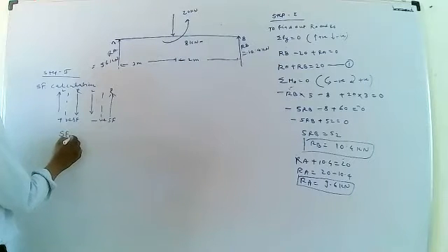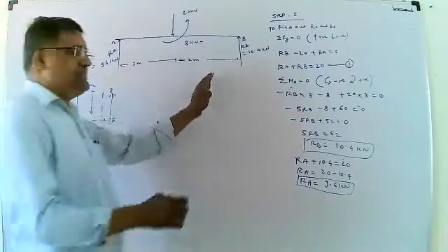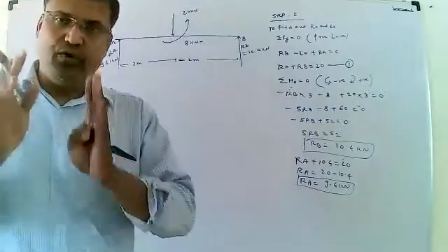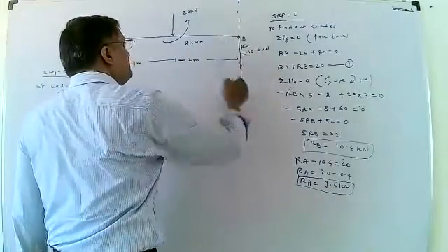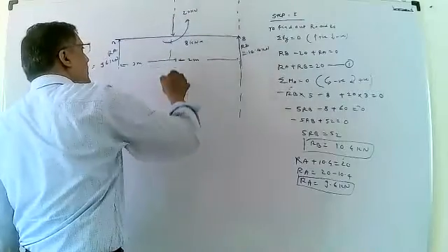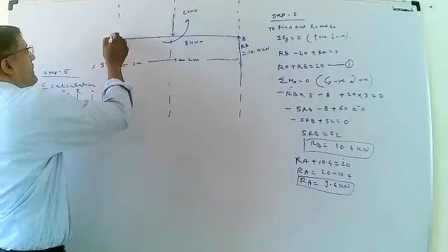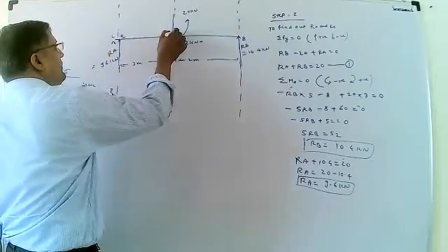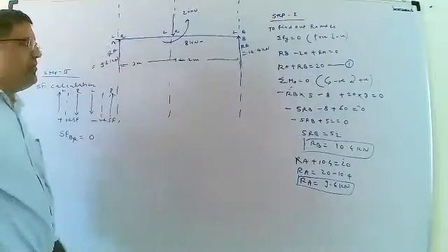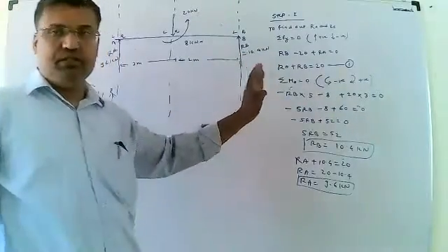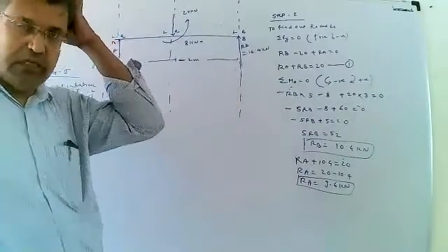Shear force at the point B, right side, is equal to 0, because first of all each point load is considered as a section, with a left side and a right side. The calculation for shear force always starts from the right hand side to the left hand side of the beam.